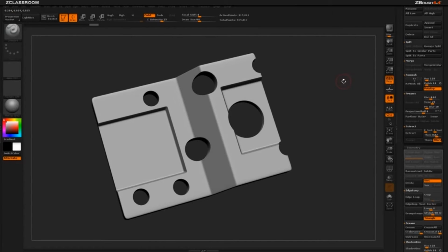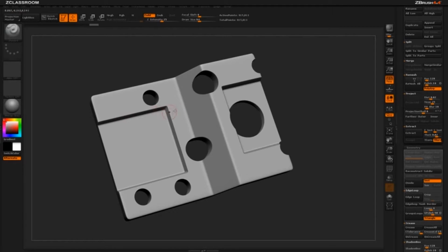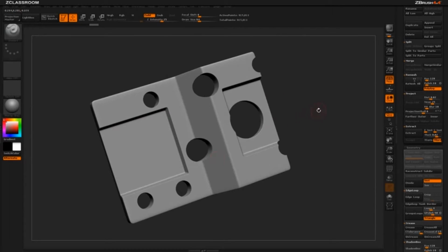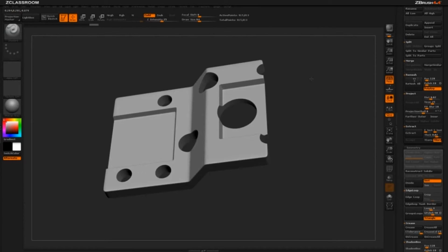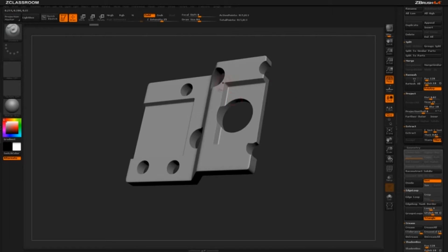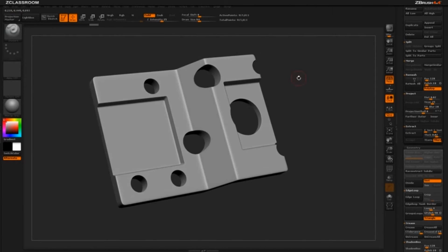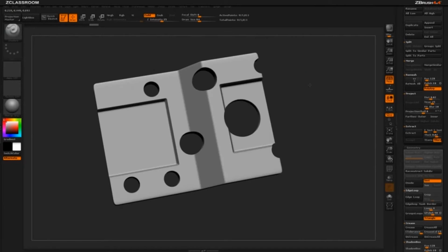The problem with remesh was that you would still have to sculpt or clean up the sculpt after you punch the holes through it. With ZBrush 4R4 and the new DynaMesh Subtract feature, that cleanup pass is no longer needed. You're now getting these precise, complex shapes that require no cleanup instantly inside of ZBrush.